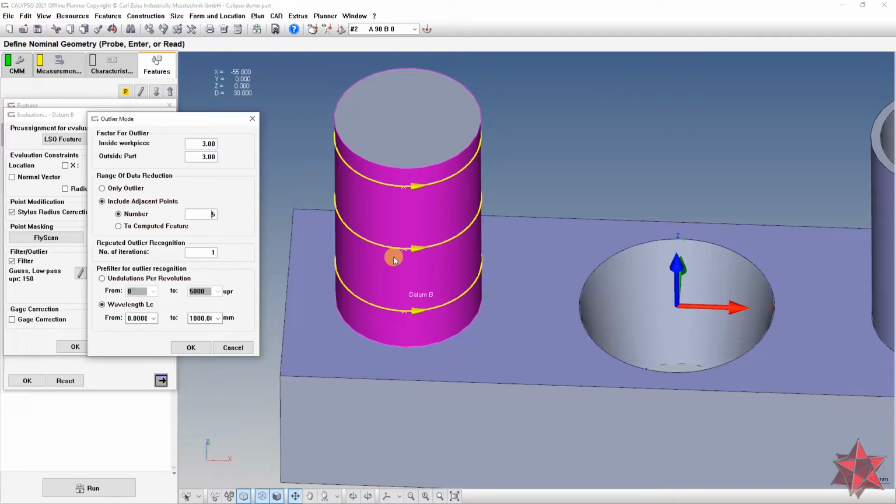You can check it, you can redo the measurement if you want. You can see all of the information in the form of the cylinder after you scan it. If the form is big, you can go and see exactly if something is wrong there. If the form is okay, then I think it's fine. But be careful here because the form can also be deceiving. Some parts have big form deviation and it can misguide you.